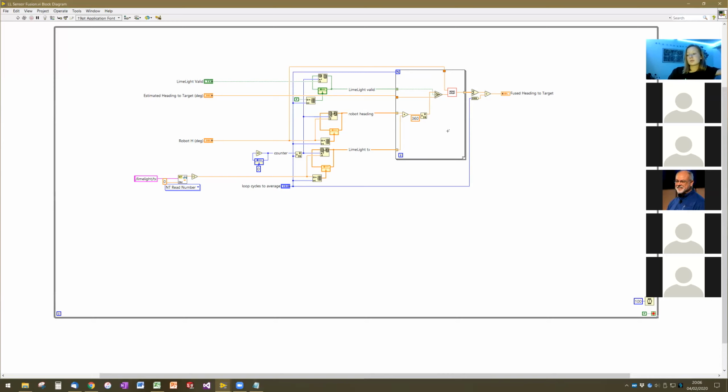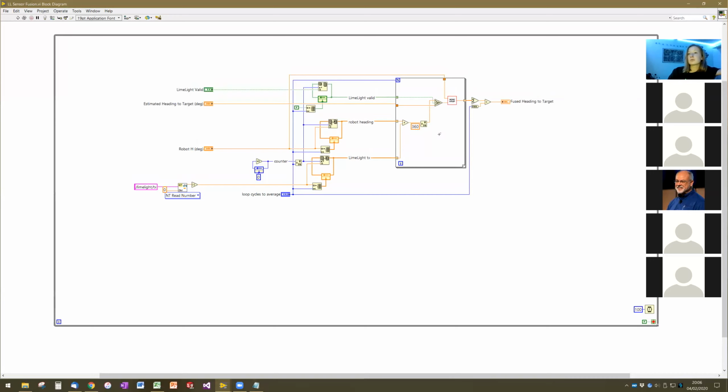Does that make sense as far as why we want to use the robot's current angle? Or are there any questions with that? So the difference between this and the LiDAR case is that, encapsulated in both the LiDAR range and the distance to target estimate, we have that current robot location.